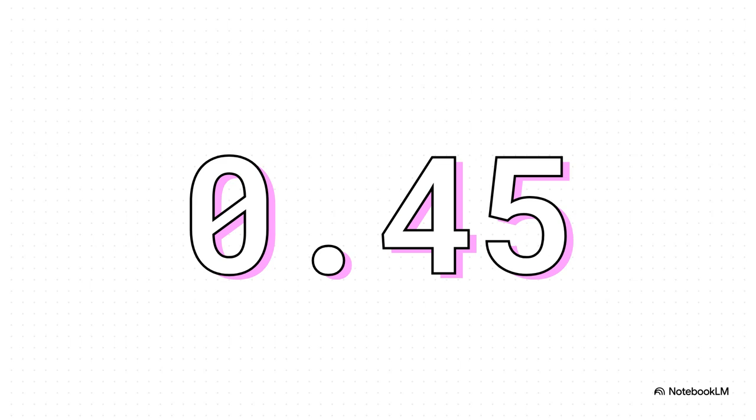If you only remember one number from this entire explainer, make it this one, 0.45. This is the maximum allowable water to cementitious materials ratio for precast concrete products. Burn it into your memory. It will be on the test.